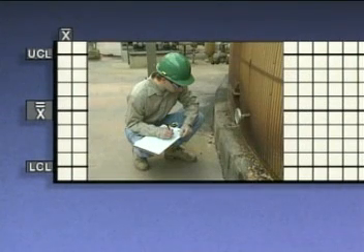The y-axis on an X-bar chart displays the average value of the samples taken from the process in the appropriate units. The x-axis displays how often samples are taken, again in the appropriate units. To see how to plot a value on an X-bar chart, we'll use temperature readings taken at 4 locations around this liquid storage tank for our sample group.